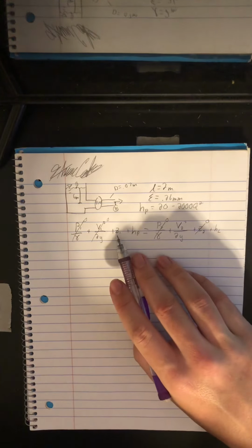So we are trying to find, for part A, the volumetric flow rate of the system, which is Q. So we can write all of these things in terms of Q so that we only have that as our unknown. So HP, we have 20 minus 2,000 Q squared. Velocity 2 is the same as Q over the area. And we also have the equation for head loss, which is the friction factor, the length over the diameter, times velocity squared over 2g. So both these velocities are going to be equal to Q over A, and A is easily calculated.